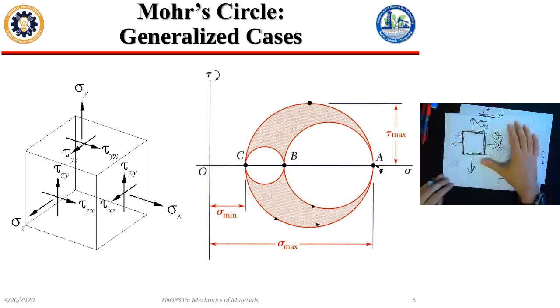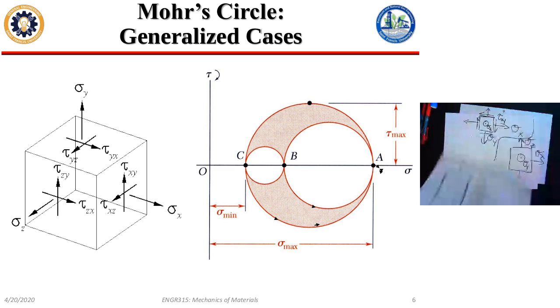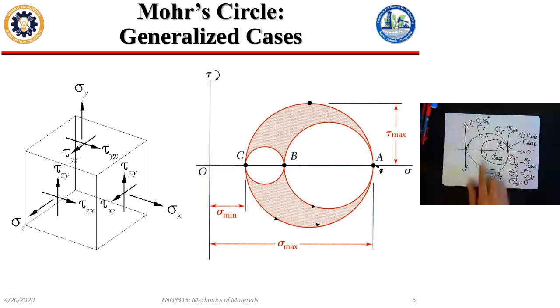Okay. So now sigma y is pointing straight up. So again, I look at this like a 2D thing. I can find an average and all that jazz. But I can also go back over here and say, well, there's sigma y, there's sigma z. That forms a diameter, right? I can just draw a circle between those two because half the diameter is the radius.